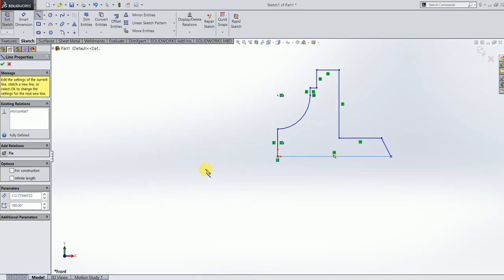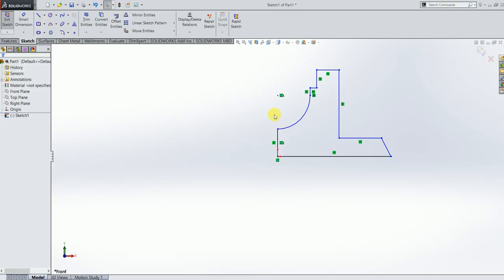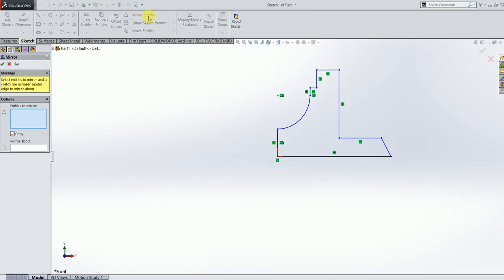So therefore, in order to add the dimensions easily for the created sketch, what I do is I will go for taking the mirror. So this is the right profile of the body in the front view. Instead of dealing with only the right profile of the body, I am going to take the mirror, and I will also construct the left profile of the body. So how can it be done? Go and choose the mirror entities here. Click on the mirror entities in the sketch command.